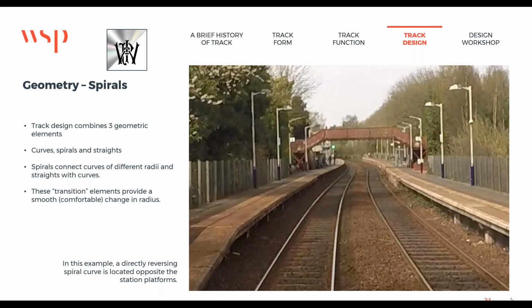Okay. So I've answered the question about the 2-second rule. The 2-second rule is there because it's comfortable. If you keep elements longer than 2 seconds, you're not constantly changing direction. It helps the vehicles, their oscillation, because their natural frequency is that 2 Hertz thing. And it also makes the designs easier to maintain and go from compliant design to good design.